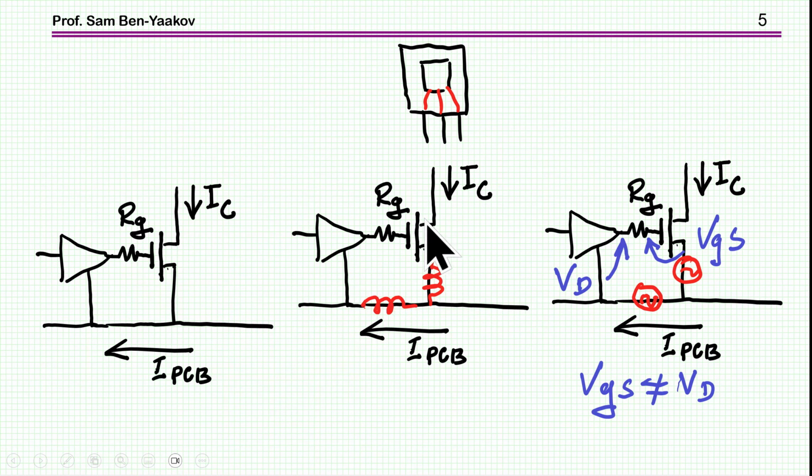So when a current is passing through them, and especially here, very high current, the drain to source, then you do have voltage drops here, and consequently, the gate to source voltage actually seen by the transistor is different from the drive. You have these two additional sources which are noise, and this could be very harmful if the level of the noise is high, and you'll be, say, passing the threshold back and forth. This could be very harmful.